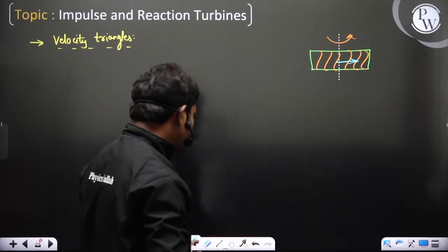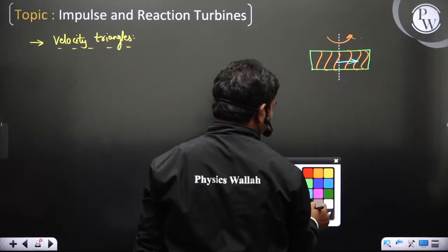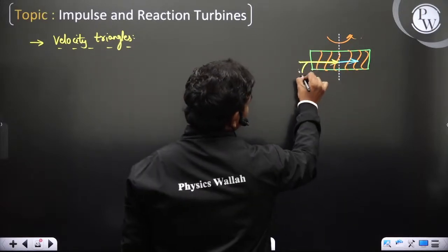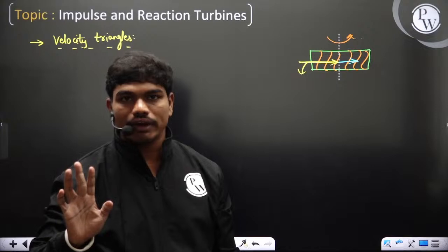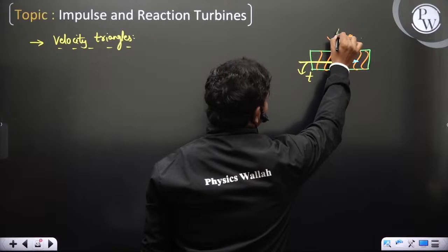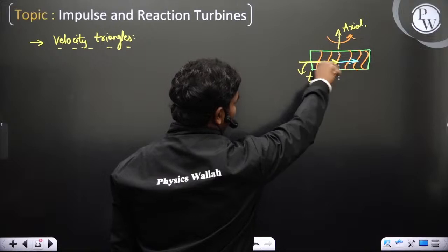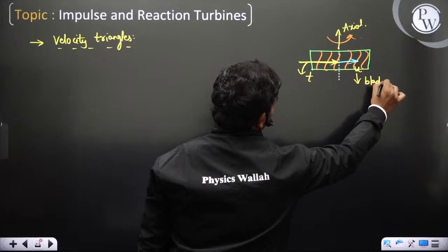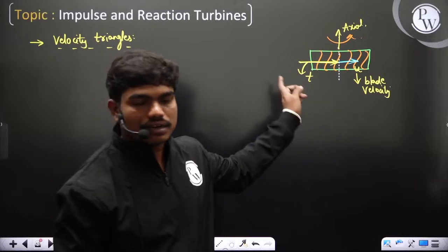Now clearly, for the rotation of these blades, we need fluid having a velocity component in the tangential direction. So this is the tangential direction in this case. When fluid hits the blade, it will definitely rotate about this axis. Is this clear to all of you till this point? This is the tangential direction and this is the axial direction. Whenever fluid particles hit, these blades will rotate at a certain velocity u, which you normally call the blade velocity. So this is how the rotor rotates.